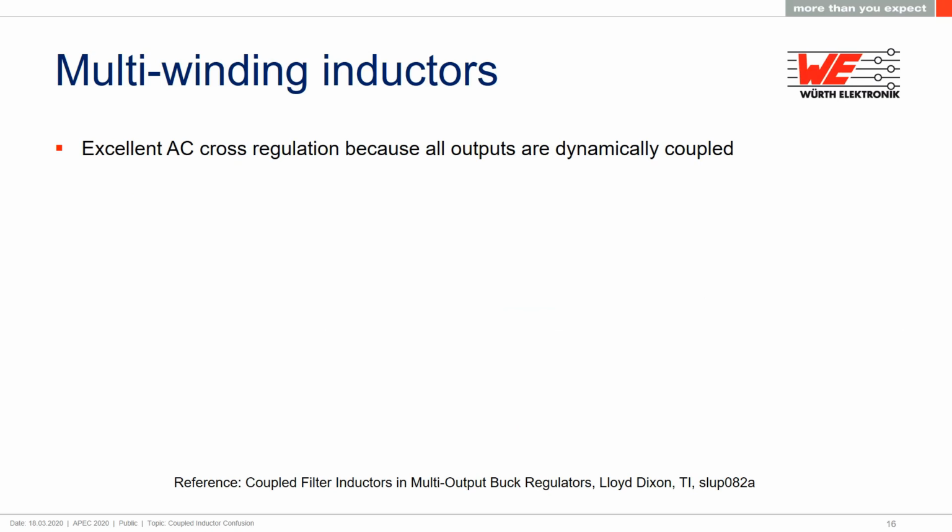Another type of coupled inductor is the multi-winding output inductor. These are used in multiple output power supplies where there are several outputs but only one is regulated. Even if these additional outputs do not require tight regulation, they can have large voltage swings depending on the loading. By linking all the outputs through the multi-winding inductor, the outputs influence each other and there are reduced voltage swings.